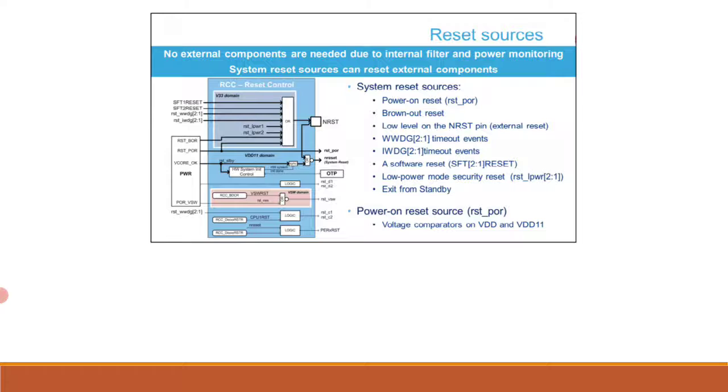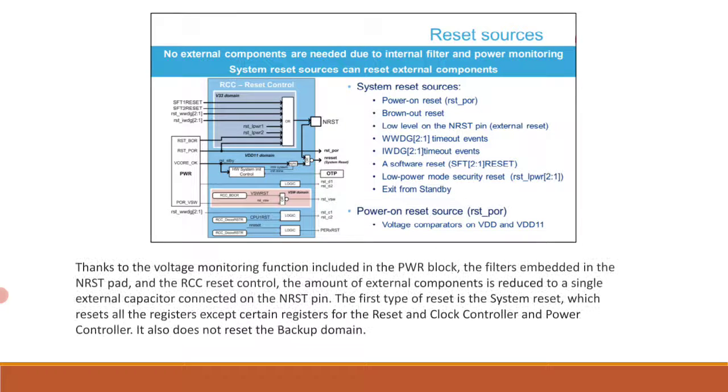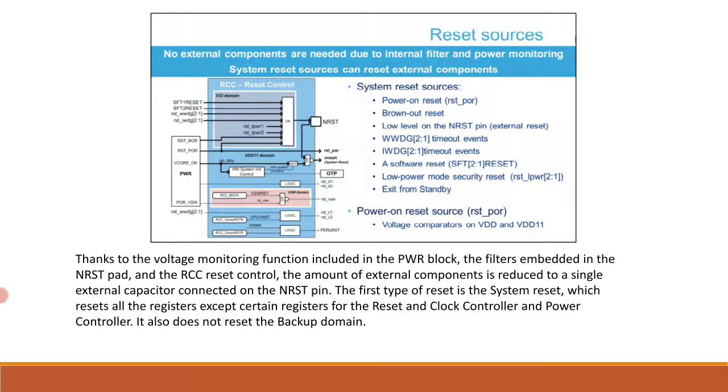An invalid voltage on VDD due to the brownout function. The brownout function allows the user to choose its own threshold levels for the VDD supply. See power block for details.